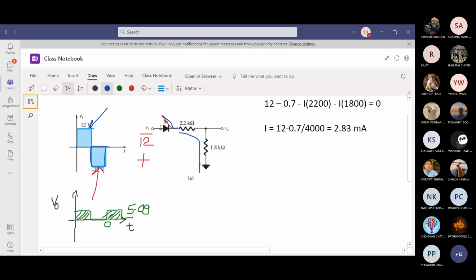It is like an open circuit. Once you have an open circuit, is there any current? No current. Vout you can take from this point to this point. If there is no current through the resistor, there will be no voltage according to Ohm's law. Nothing will be sensed at this node. No voltage.